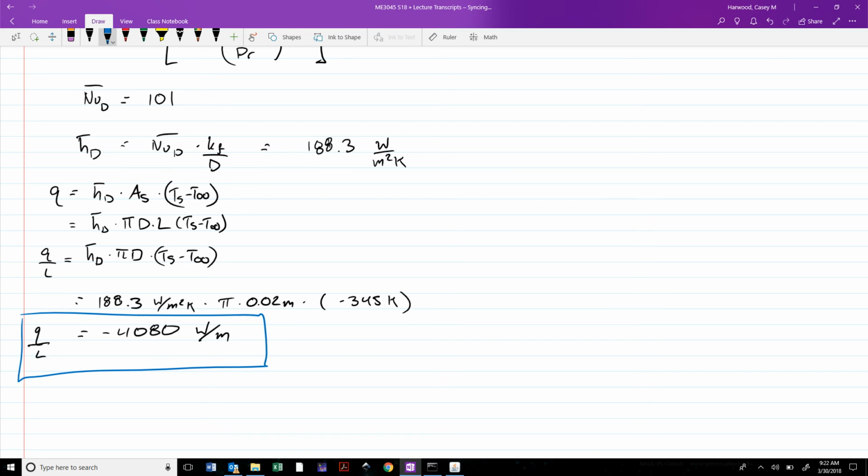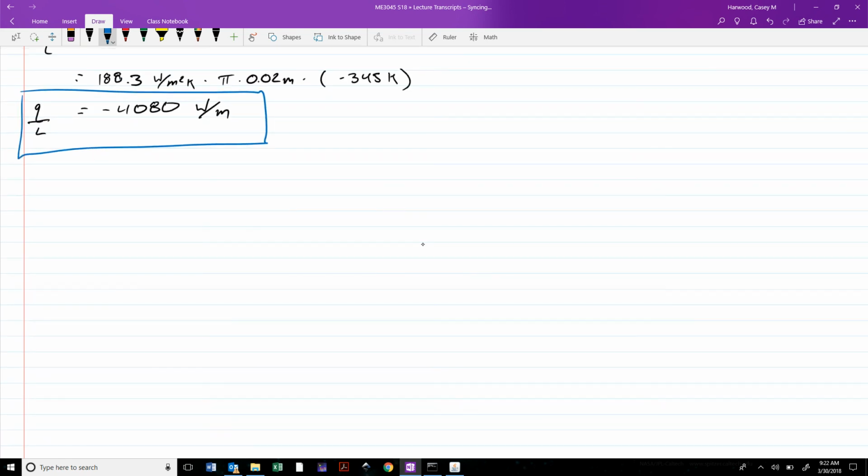So for problem B, you know the temperature distribution. Apply Fourier's law at the bottom plate. You've got your temperature as a function of y, and you can say then that Q is equal to A times k sub f times dT/dy at y equals 0. That's Fourier's law. That's how you can find the heat rate.